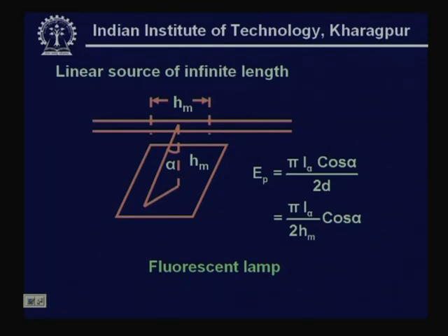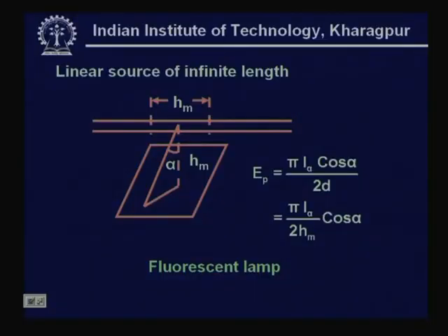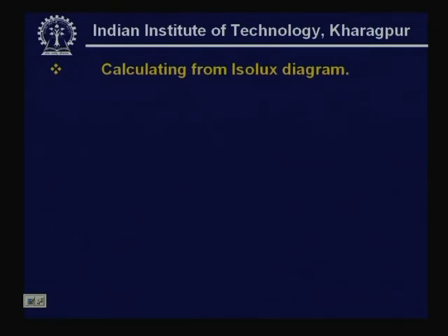In case you are able to create a large sheet of light source, that is by having a number of fluorescent lamps together, or alternatively a matrix of incandescent lamps as point sources, put in a single luminaire with a diffuser, then it would be independent of the mounting height or the distance, and you get a uniform light on the work plane.